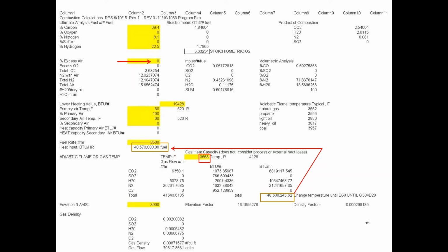So very expensive. That being said, so anyway, if I take so many pounds of all these gases and apply the heat content in BTUs per pound, because I know how many pounds I generated, and when that number is equal to the input heat, that's what they call the adiabatic flame temperature. I see. Of course, I don't do this by hand anymore. So up there in the left-hand corner, we put it into a little Excel program, not a complicated computer program by any means. We put in the composition of natural gas.